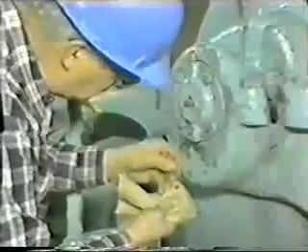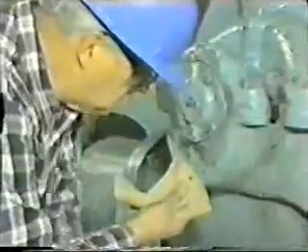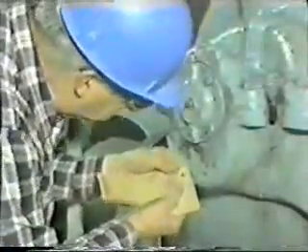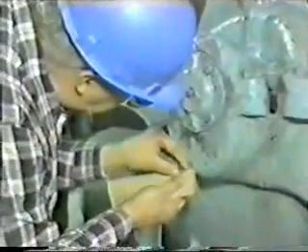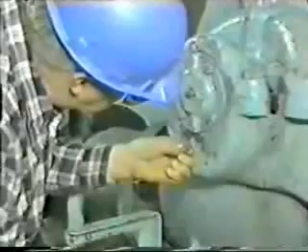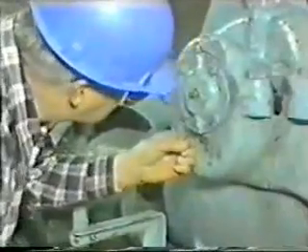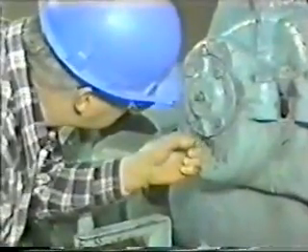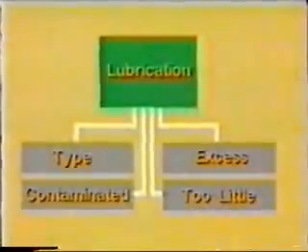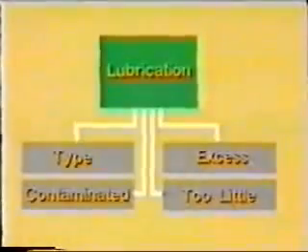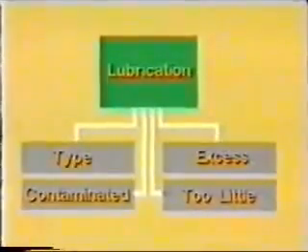Look carefully at the smear. Can you see any signs of contamination? Do you see any pieces of metal? Pieces of metal might indicate that the bearing may have been damaged and could fail. If you don't see any pieces of metal, rub some of the grease from the smear between your finger and thumb. Can you feel anything gritty that might indicate contamination? Gene didn't see any bits of metal or feel any dirt. He thinks that contamination is not the cause of the problem.